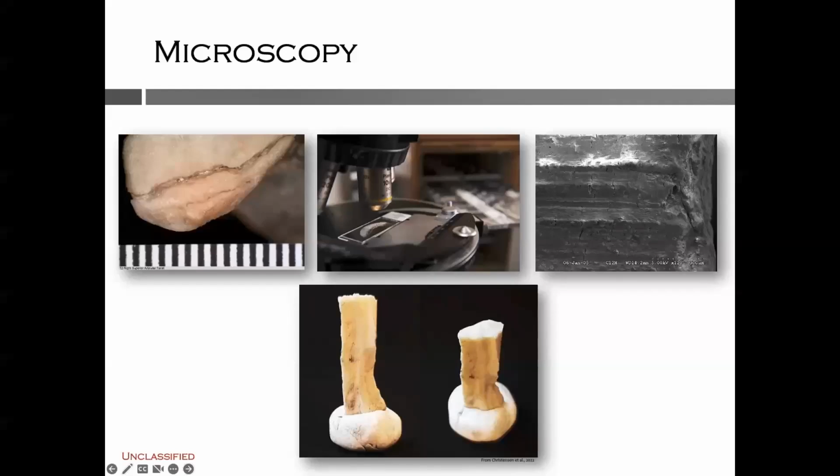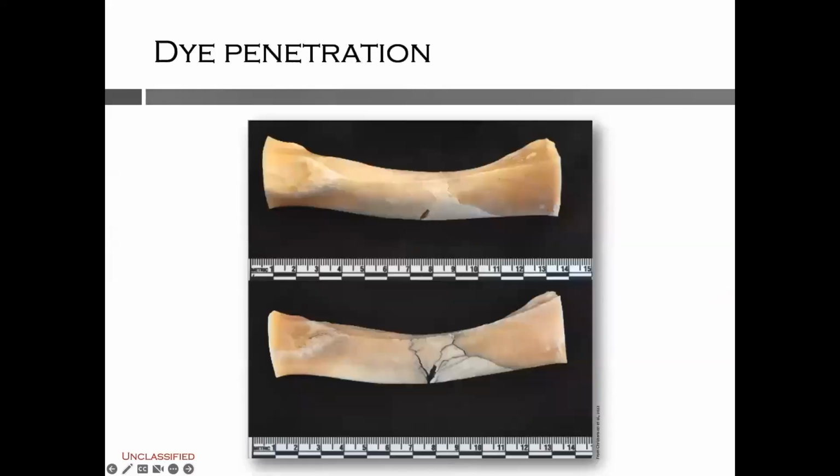Note that polymer clays are recommended over conventional sculpting clays because sculpting clays can blend into fracture surfaces and can be difficult to remove. Polymer clays can be removed more easily, and anything that adheres stubbornly can be removed with acetone or ethanol. The use of contrast media can help to accentuate features or increase observable detail, and this can be useful for visual examination as well as photography and microscopy.